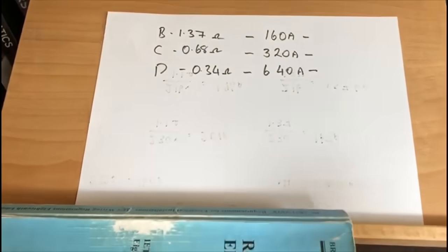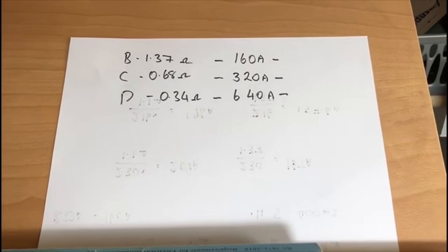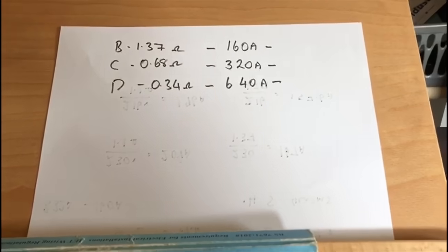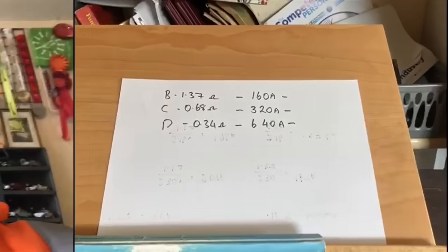So I hope this video may help doing some of the calculations for your design or inspection and testing, but that's basically the relationship of the earth fault loop impedance. So basically, just to sum up the video, talking about the earth fault loop impedance, hopefully I've cleared up a few things, just explaining with the 80% and the 100% value, and how important it is that we adhere to the 80% value when we are actually on site working.